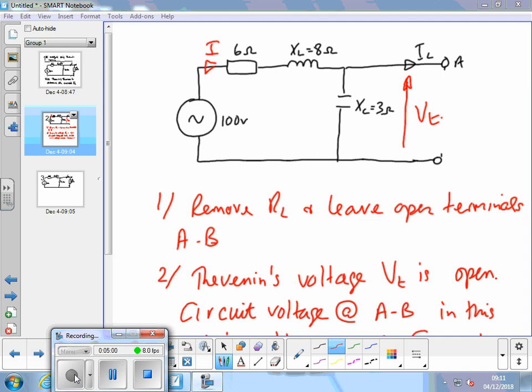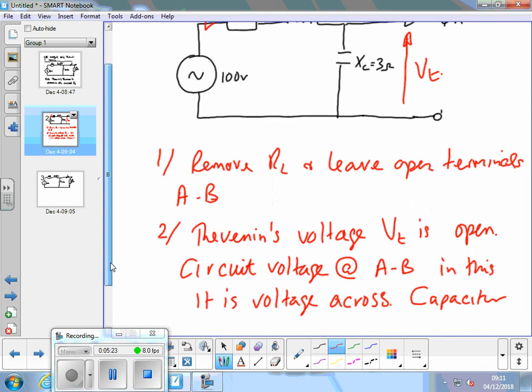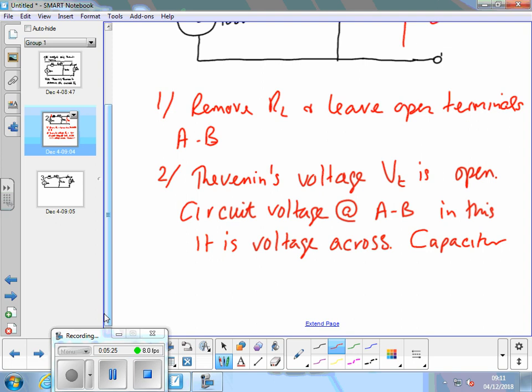We know that there's only one current in that circuit at the moment because we've taken the load out. When the load is in, there's a parallel circuit, but with the load out, there's no parallel circuit. So we've got a series circuit around here with one current. What do we need to find out first before we can determine the current? Is it resistance total?